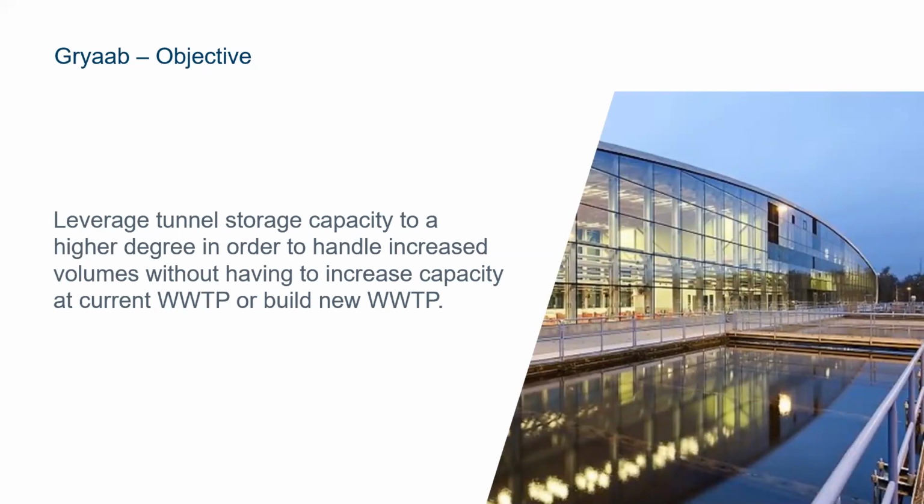And to determine the recommended control strategy, Future City Flow uses an algorithm to optimize the pumping scheme to achieve inflow to the treatment plant that is as constant as possible during the coming 12 hours, while still considering boundary conditions such as allowable water levels in the sewer, pumping capacity, and pumping conditions. Simulations performed at the beginning of the implementation indicated that the discharge of untreated wastewater could be reduced by as much as, I think, 50% in the Gothenburg case.